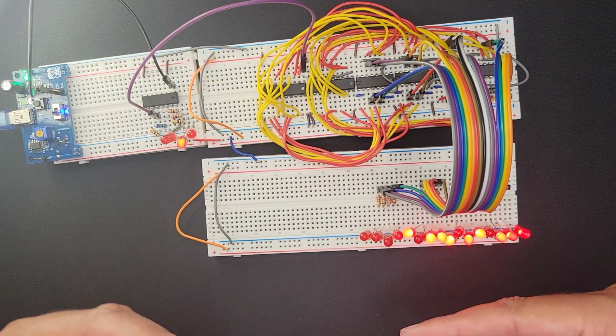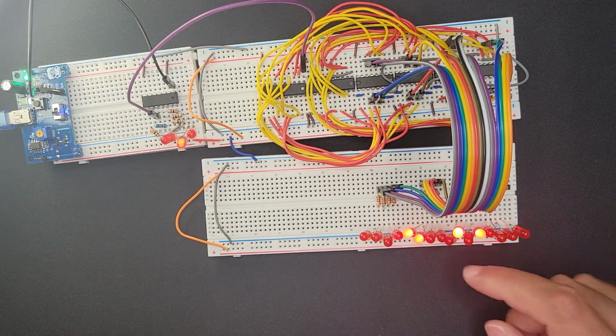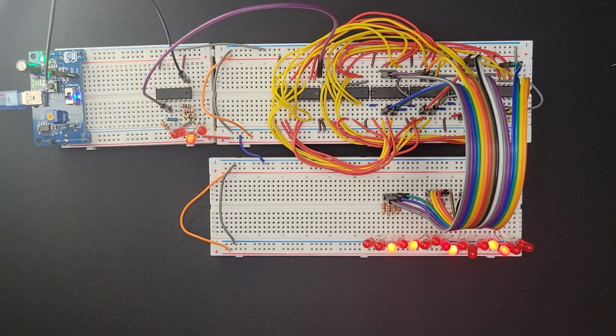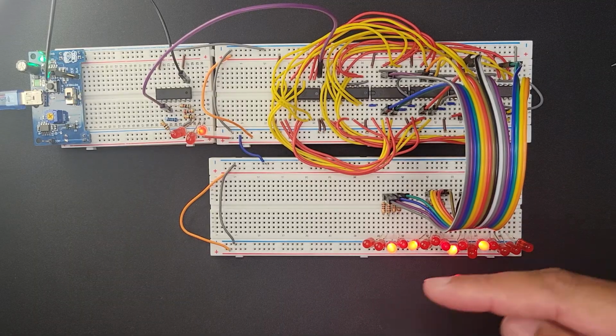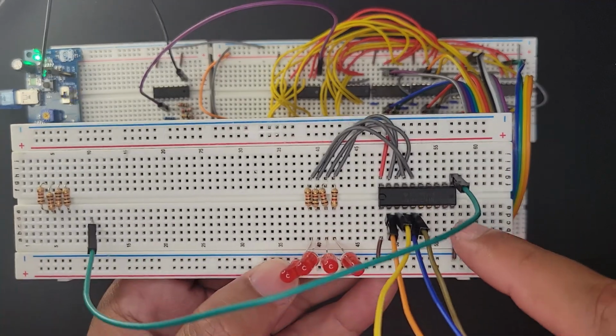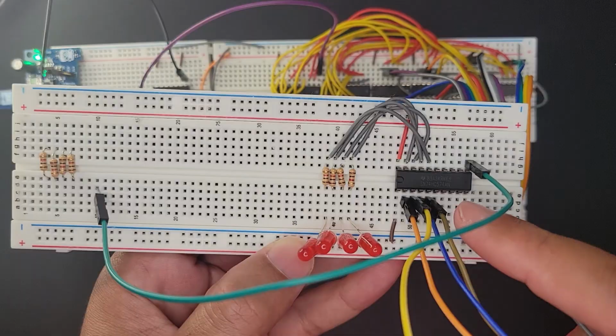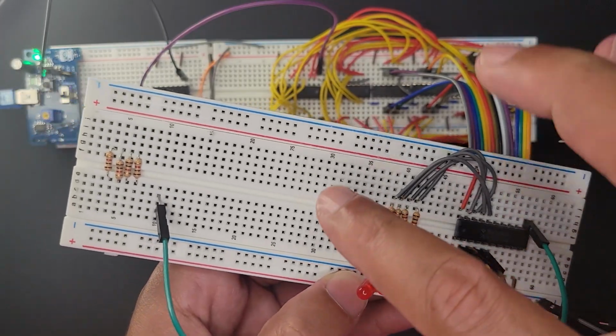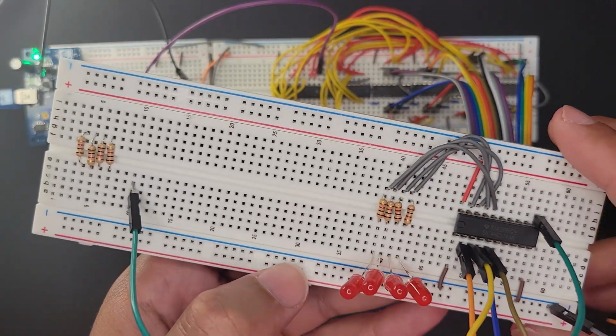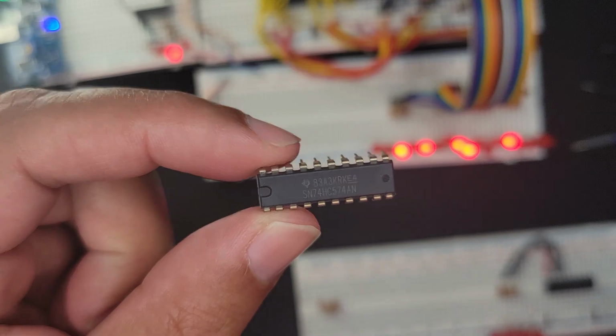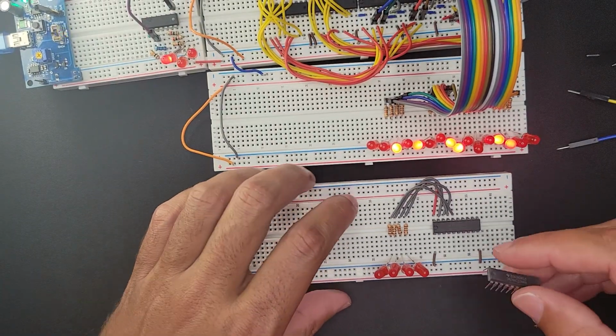Unfortunately, I undid what we had before with the instruction memory address register. I'm going to call it the IMAR. We had the IMAR earlier set up, but now that it's 16-bit, we just have to do it again. So I guess what I'll do is I'll add another one to make it 16-bit and get it working again. I'll put the display port next to it, so we'll have its own display port built in. All right, here's another 574, so I'm going to put him next to the existing one.